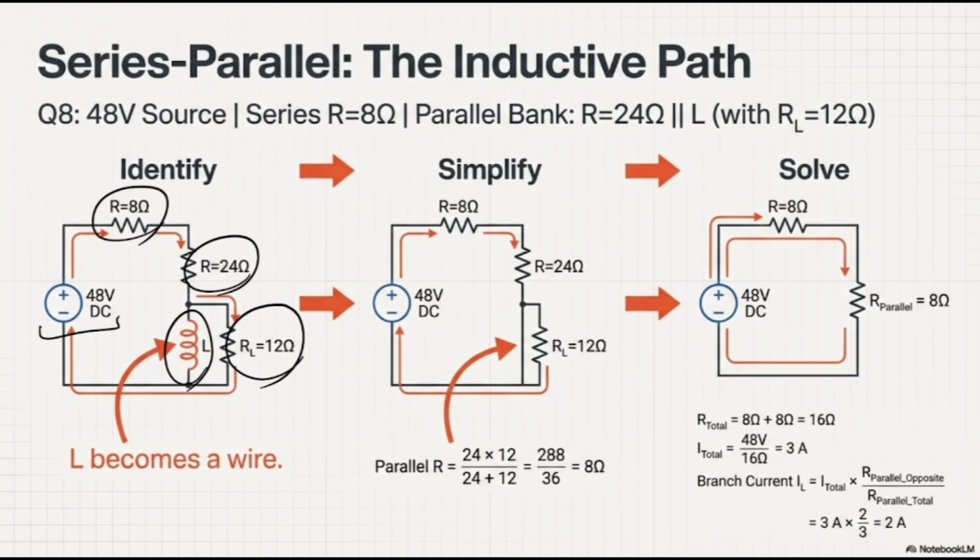So what do I have right now? I would like to find what would happen after 5 tau or after infinity. Obviously after infinity, your inductor is just a short circuit. While the inductor is a short circuit in parallel with your resistance, what do you have? You have a wire, so the current is not going to pass through those resistors, because it would like the least amount of resistance in order to pass, right?